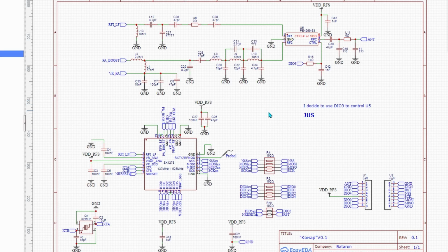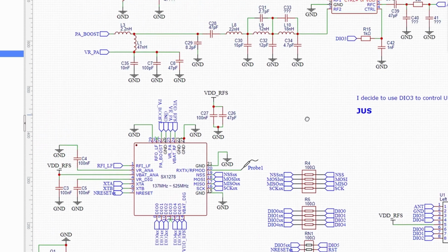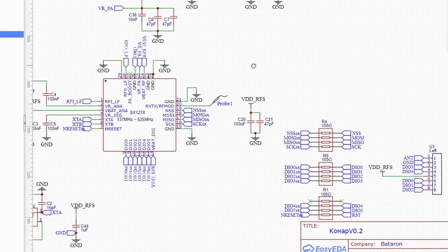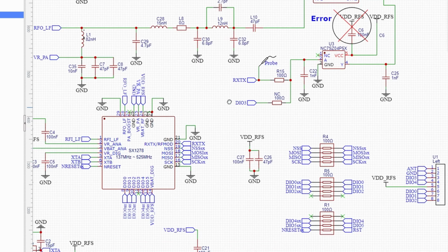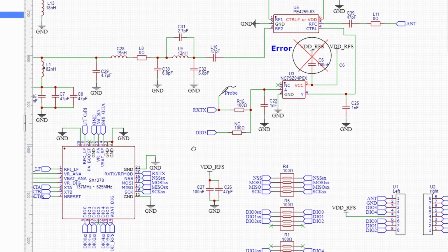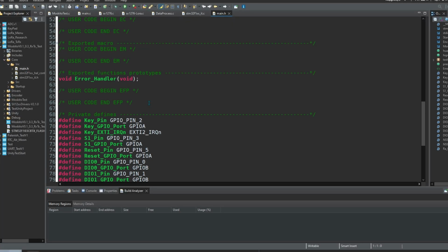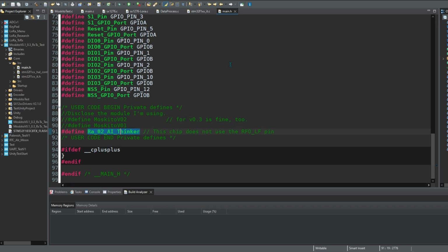In this part, we will consider the code we used for research of communication quality. All three homemade LoRa modules have different circuit diagrams and topology, which influenced the program code. We took these differences into account by means of conditional compilation. Depending on the scheme used, we can set the flashing variant by changing directives in main.h. Changing directives leads to change in the compiled code.